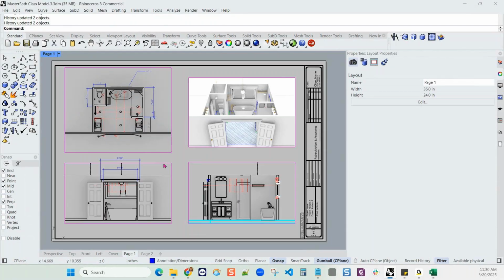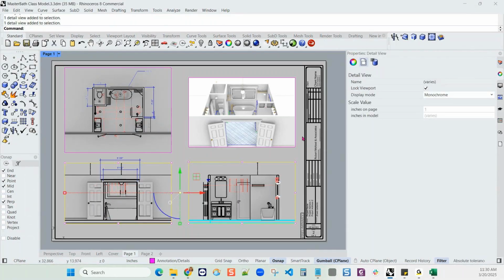Now, once you set the scale, you need to lock the detail. So this one here, I'll set to 16 like the other one. They didn't change much, but they were actually just slightly off from 16. So when you're done setting the scale, then you lock it.